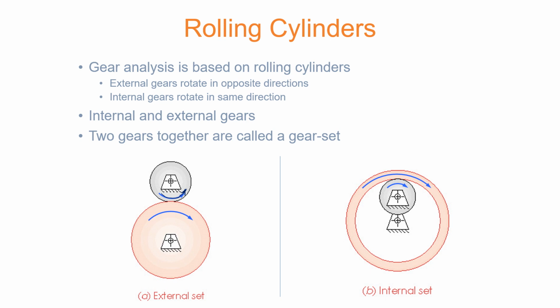So this contact is ensured at this particular point. And since the input is going to try to force the lower cylinder to rotate, using our common sense, we can visualize that the direction of rotation of the lower cylinder is going to be reversed. And that's a very necessary condition to follow.